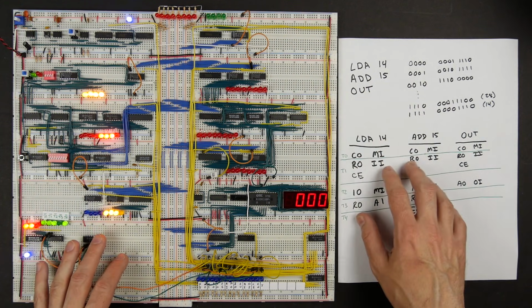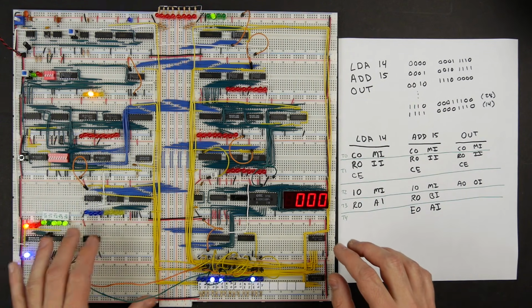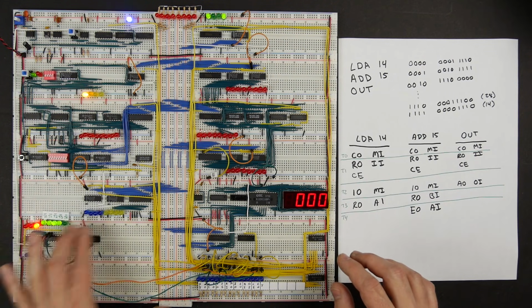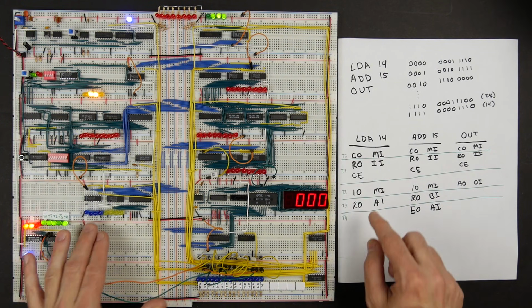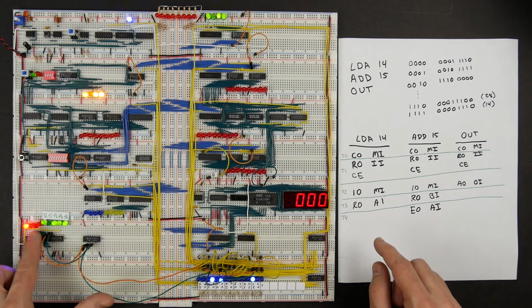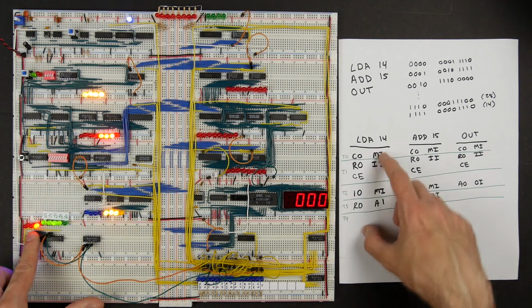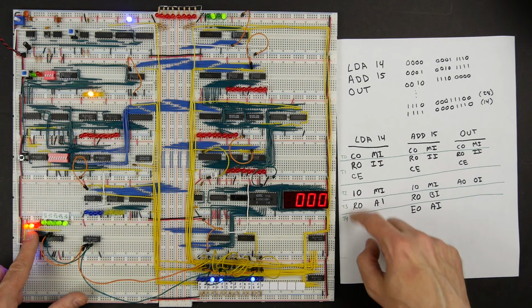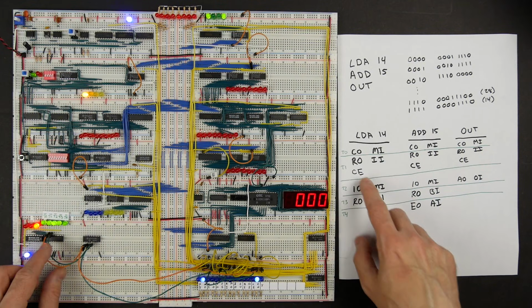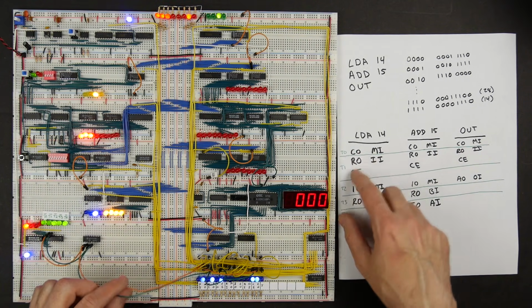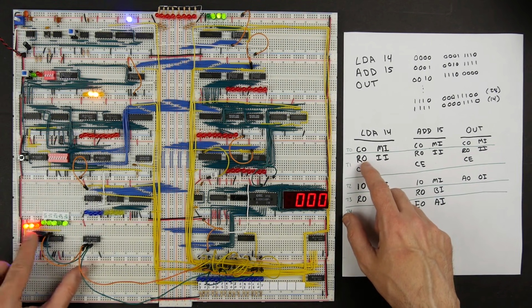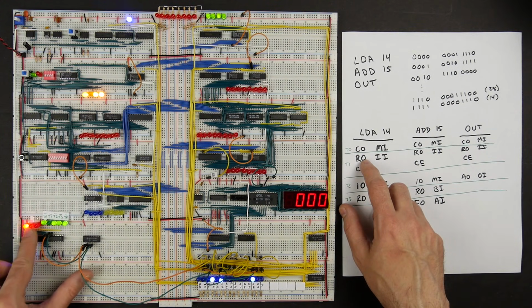And so in order to understand how that's going to work, there's really 2 pieces of information that feed into what control signals need to be active at any point in time. And one of those pieces of information is which step we're on here. So which of these time steps we're on. When we're on T0 or T1, we have signals that indicate that. But that's one piece of information. So where we are in this count is one piece of information.